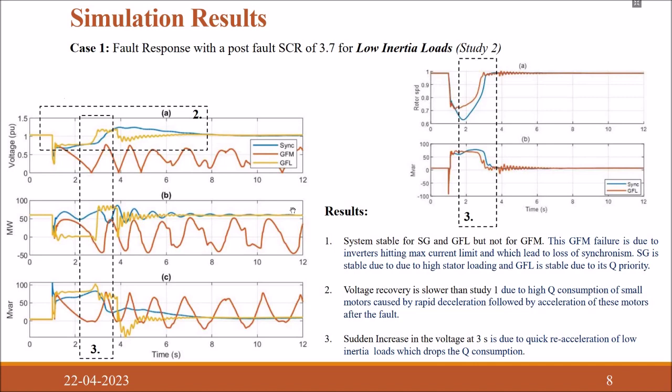Now if we compare the result, the voltage recovery condition, with the cases in the previous study, which is study 1, we see that the voltage recovery is low, and this is because of high consumption of small motors. Because of small motors, there is a rapid deceleration which is followed by acceleration during fault.